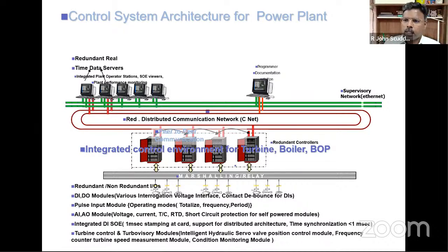And when that trip happens, what we do is we immediately stop all the control valves and stop valves of the turbine. We give a close command. Or if there is a common trip oil which can close off all these valves, we drain that oil. By draining that oil, everything closes.